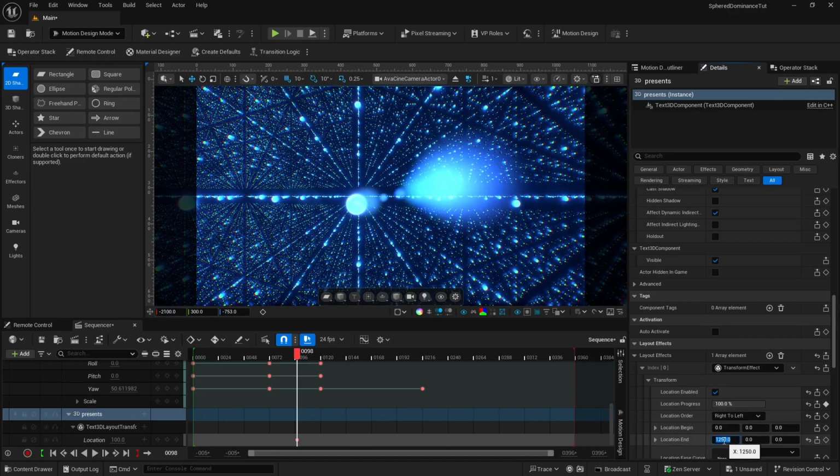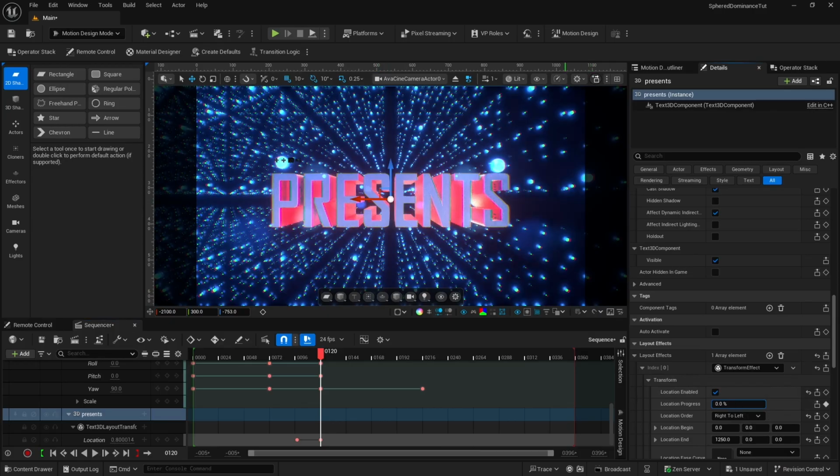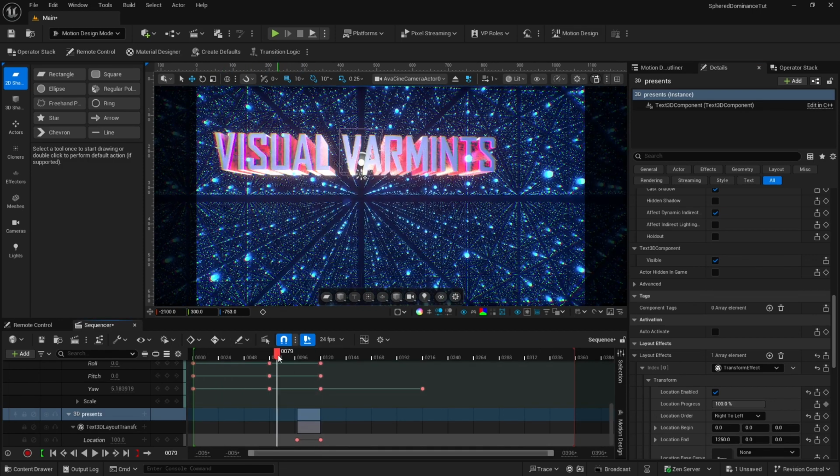1,250. And we'll leave the others as is. And now we'll jump ahead to 120 in the sequencer, and that's where we'll end this. So by setting that location end right there at 1,250, we pushed the text away from the camera. And now with the location progress set at 100%, we're going to drag that down to 0. And you'll see that that's going to animate all of that text in towards the camera. So now with it set at 0, we'll set that second keyframe, and it's already set for us because we are using the auto key right there. And so now let's jump back and take a look at that.